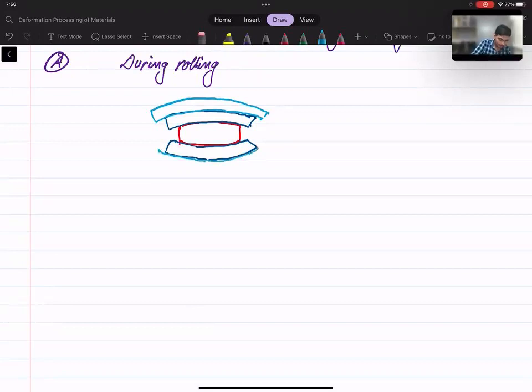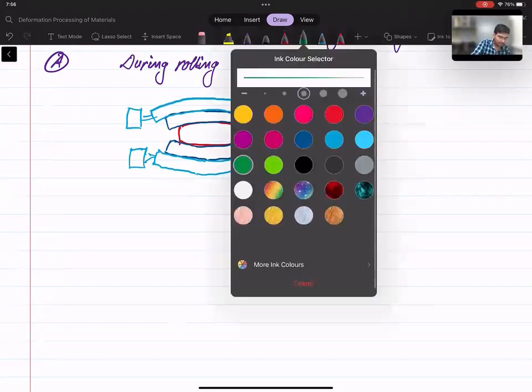So what happens here is you can see that the rolls are not parallel to their axis, or they have got bent to some extent. Suppose these were connected to bearing houses as we had seen earlier. So these are connected like this. Okay, so you can observe that the thickness is not uniform.